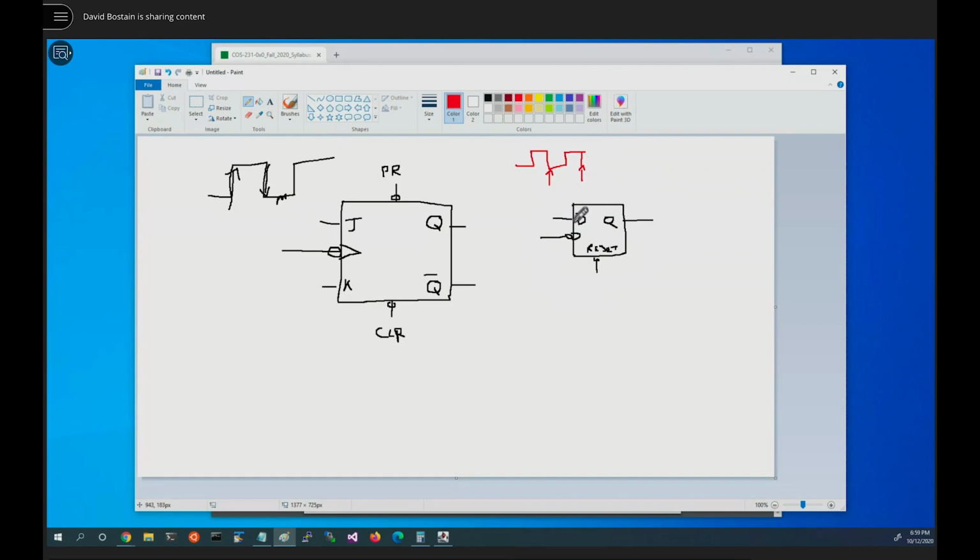It happens to be a D flip-flop. So it's an edge-triggered D flip-flop, triggered on the falling edge, with an asynchronous reset. We don't need to mention the fact that it's low going because that's almost implied, but we would look at the schematic to make sure. And it only has a Q output. It does not have the inverted Q. So we could fairly well characterize that. If that's what we needed in our circuit, we could go find that and we could buy that. Let's do another one here.